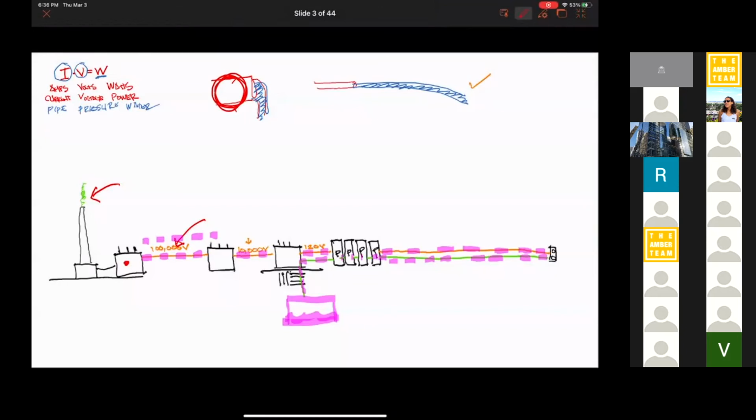Now we can step up and step down direct current, but I think actually the way we do that is we transform it into alternating current first. It's actually called inverting it. We invert it into alternating current first. Then we use a transformer to step it up or step it down. And then we use what's called a rectifier to send it back to direct current. So even now, as far as I know, we have to turn it into AC current to step it up or down, but we can pretty easily now go between AC current and DC current in a way that we couldn't before at the scale. Anyhow, so that's alternating current.